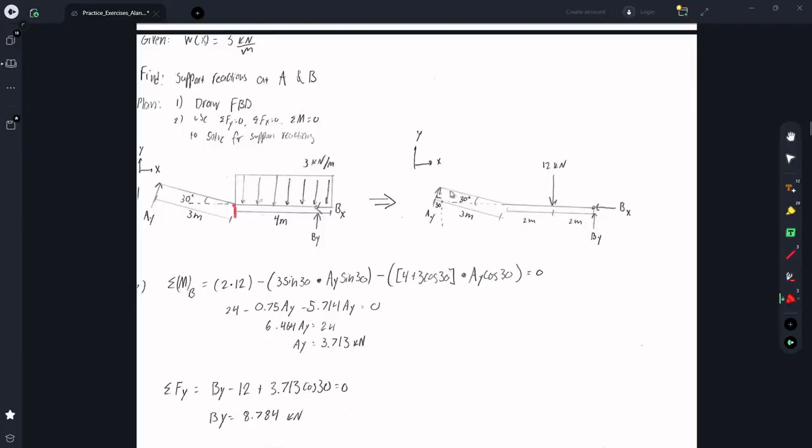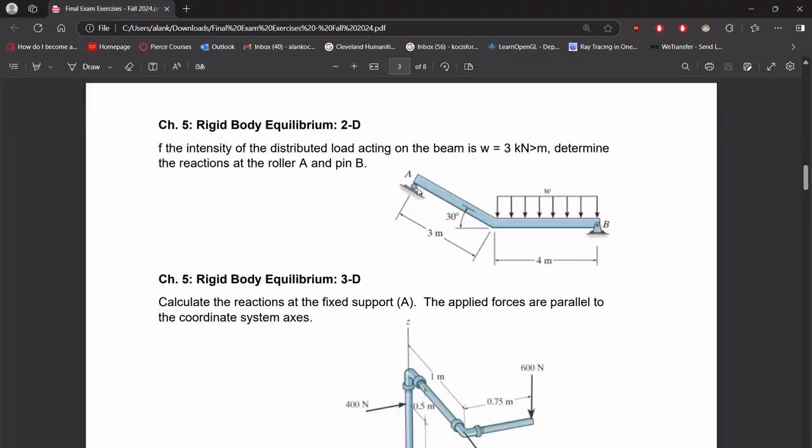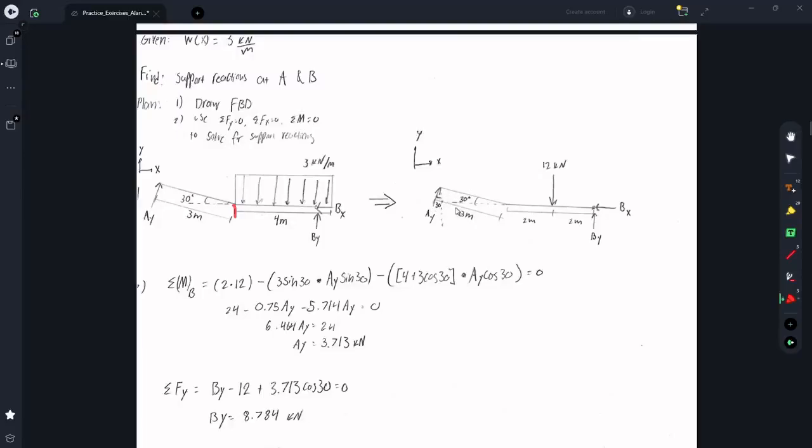Another thing of interest from the free body diagram is this angle, 30 degrees. Because this support, I believe, is a roller, it just has a normal force that goes perpendicular to this bent part. It's basically like thinking this is the angle the ground is at, and this is the normal force perpendicular to it. So if you think of this as rotating down to this part being flat, this angle disappears. And so that angle is going to be equal to the angle of the incline.